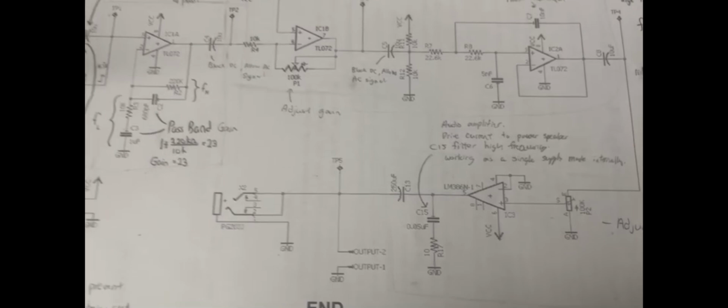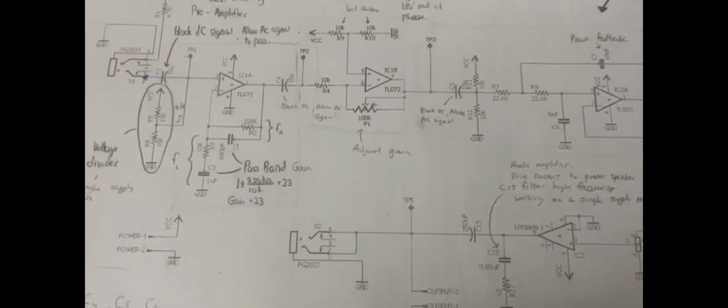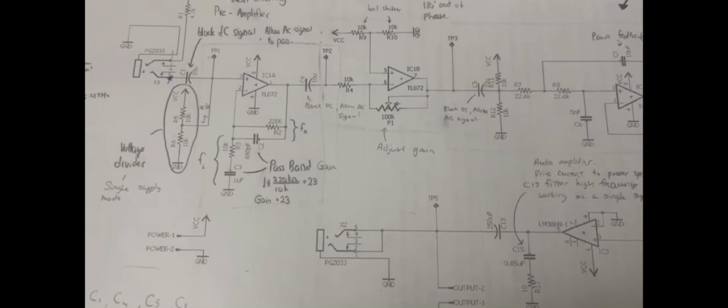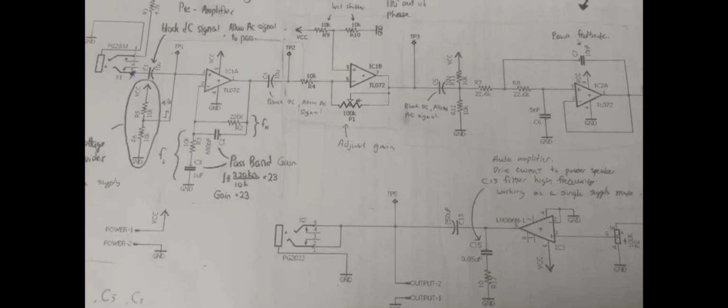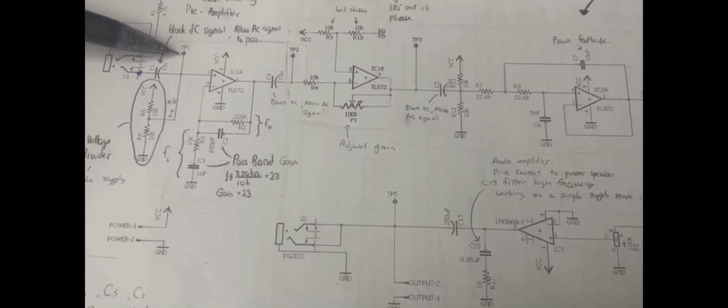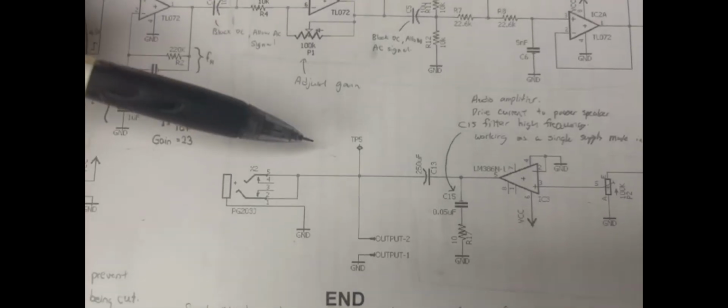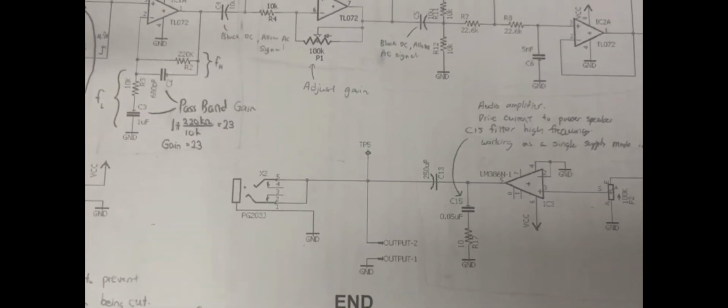For our final test point, TP5, we'll be using TP1 as our input. We'll be testing two different frequencies, 1 kHz and 200 Hz at 200 mV peak to peak. The same procedure as our past test points: we connect one oscilloscope probe and the function generator to TP1 to give it its input signal and to measure the input signal. The other oscilloscope probe is then connected to TP5 to test for its output signal.